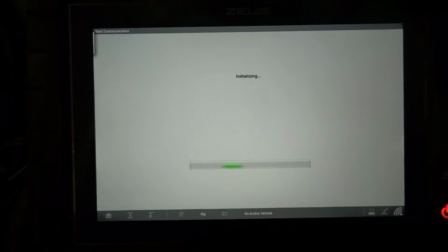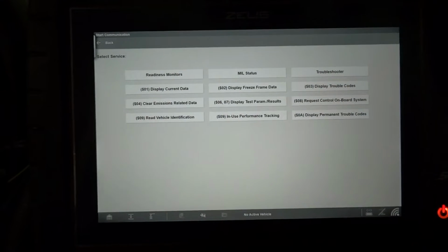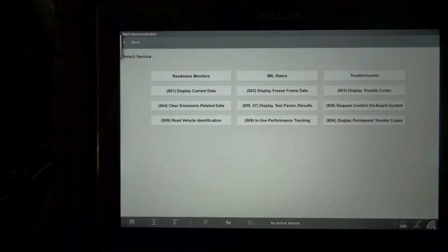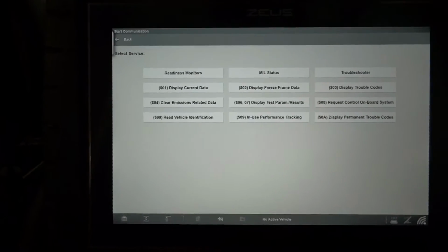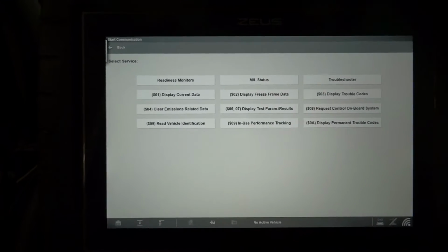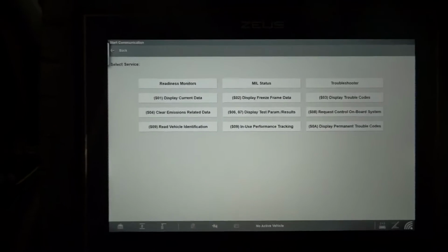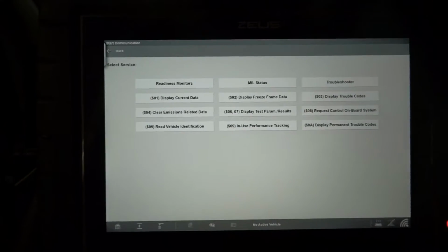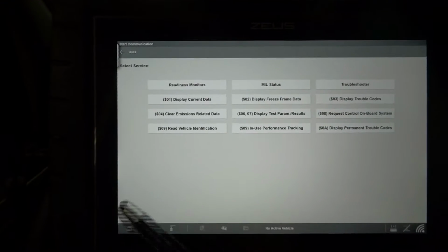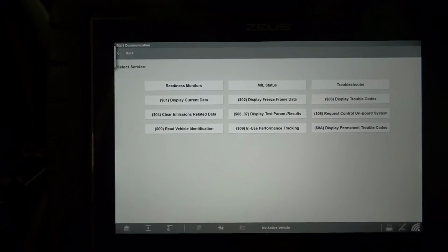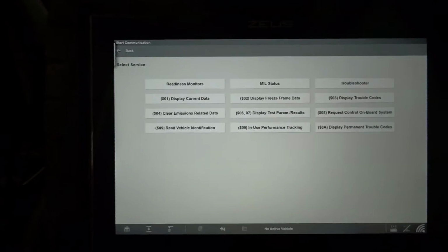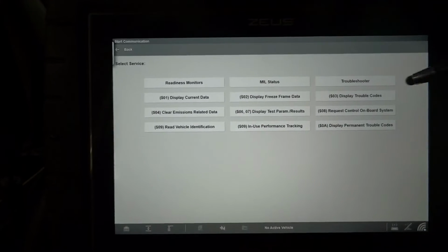So at least we have some sense of direction. We know our issue is probably around the mass airflow sensor, but I'm curious about that other code we had. Remember the code we had on the OE side? The one that said something about the EGR? The 2355, that weird code. So let me go back there, and we're gonna go to service information and look those up and see if those codes are caused by this mass airflow sensor code.